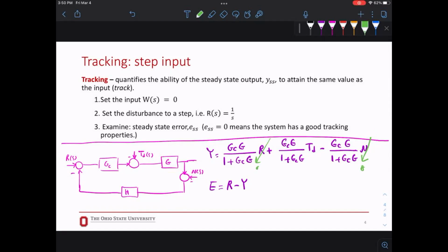Okay, so if you follow this, it would work for all of your systems if you can rearrange them like that block diagram: controller, your process noise usually shows up there, your plant and your sensor. Now, what if my block diagram was in front of my summing point?